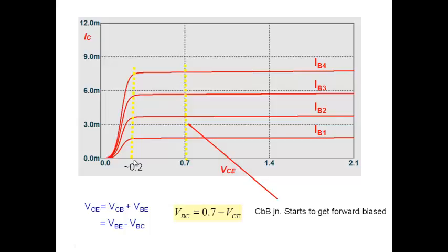So you may push your collector emitter voltage as close as 0.2 and still ensure that your transistor is virtually, not strictly according to definition, acting as if it's in forward active mode. Okay? So that's something to remember, that there is a voltage up to which you can push the collector emitter voltage. And as you push it up to that value, the transistor is effectively in forward active mode. But once you go beyond that, the current falls very rapidly.